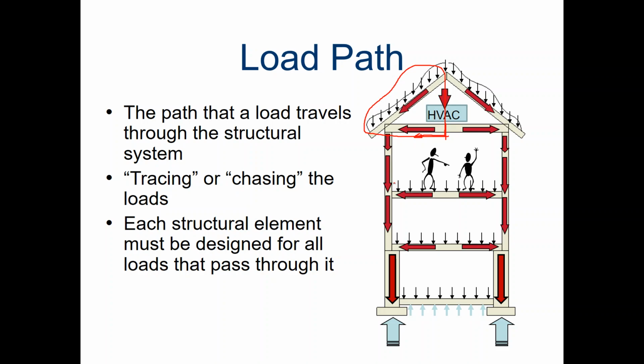All right. In turn, this column then is being held up by this column here. And so this column that I just circled here is holding up the column above it, as well as all the stuff above that, as well as roughly half of the floor here, which will chase in this direction over to this column. So as you can see, we start at the top and calculate what the dead and whatever other loads are, and then we work our way down, and with each level that we go down, we have a whole pile more loads.